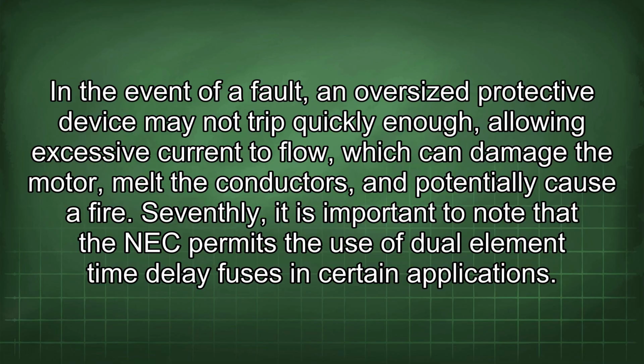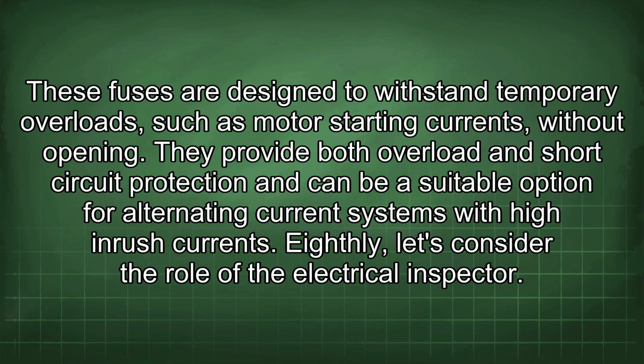Seventhly, it is important to note that the NEC permits the use of dual-element time-delay fuses in certain applications. These fuses are designed to withstand temporary overloads, such as motor starting currents, without opening. They provide both overload and short-circuit protection and can be a suitable option for alternating current systems with high inrush currents. Eighthly, let's consider the role of the electrical inspector.